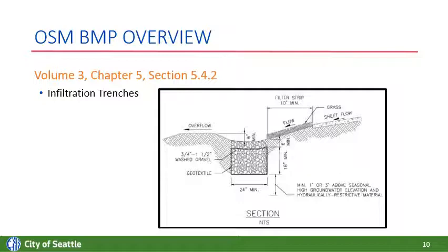So for the requirements for elimination of an overflow from a site, essentially you would need an engineer to model the facility to show that the entire 158-year simulation period rainfall is being infiltrated on site for a project to eliminate an overflow for the BMP. Removed was a yard drain option for flow entrance and pre-settling. For the infiltration trench, it will have to be a catch basin.